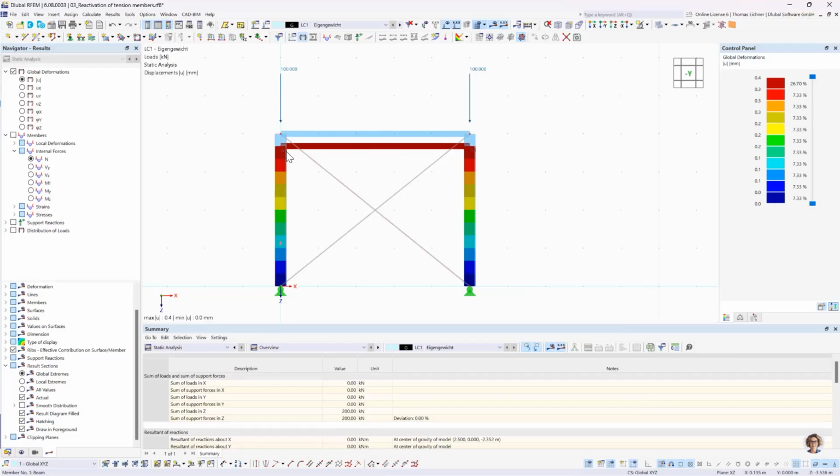The system is just going to deform in vertical direction. That means these tension cables would shorten. That means they would need to take pressure, and that means they are gray now since they both failed. Now, what we want to do is a second order theory analysis.